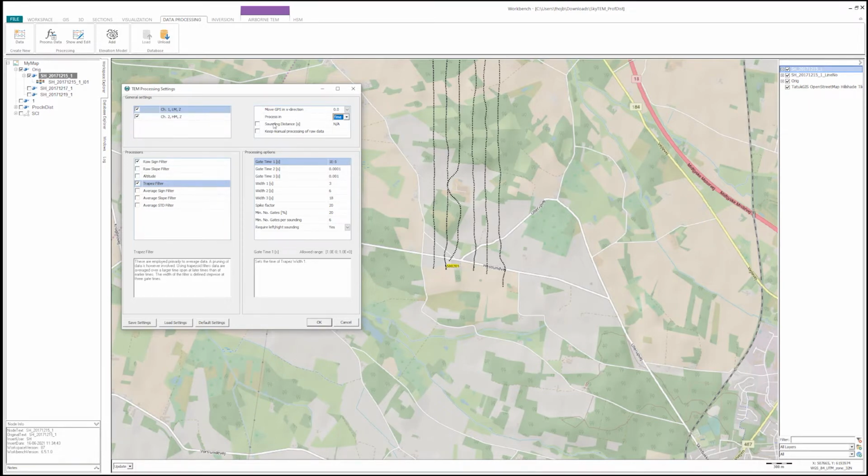Sounding distance: if you have very raw data and you want to even out during filtering the location of the data, you can actually go in and say, I want a new data location for every, for example, 1.5 seconds. So when you have done the filtering here, then the average data will have a new data location for every 1.5 seconds. It's also possible to do in distance by meter. If you want to keep the data location as it is, we shouldn't put this on.